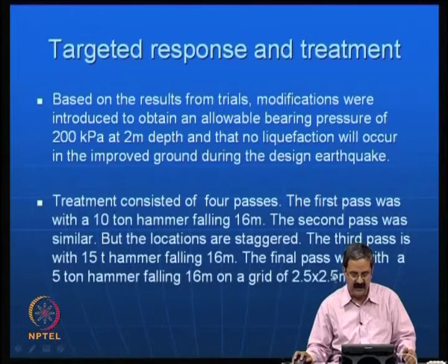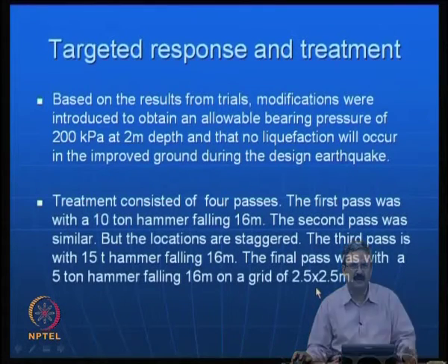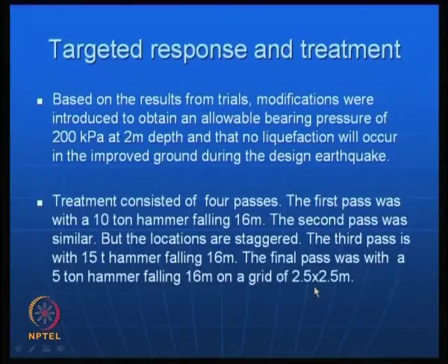And finally the last one was made with a 5-ton hammer falling 16 meters on a grid of 2.5 by 2.5. Actually in the beginning itself I said, if you make the spacing closer, then you have shallow depths densified. If you go a little deeper, the deeper materials get strengthened. So these concepts one can use and come out with some good improvement.